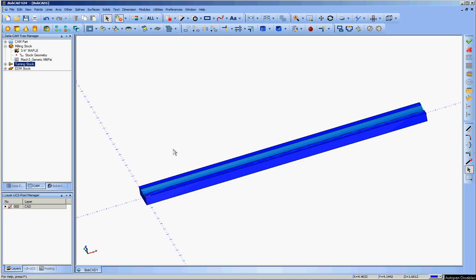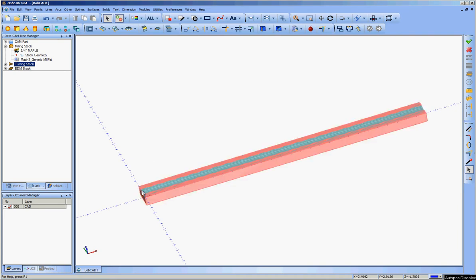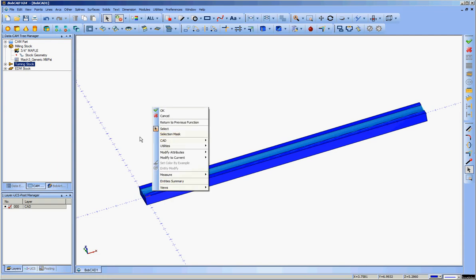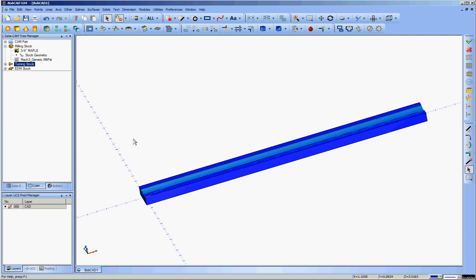The question was, given a mold for a sailplane fuselage, how to limit the toolpath just to the area that needs to be cut. And the answer is boundaries. I'm going to incorporate some of the things in recent videos by Apollo and Burman, who respectively talked about selection masks and the use of layers. So I've got a mold, I've got it set up, I've got my stock set up.